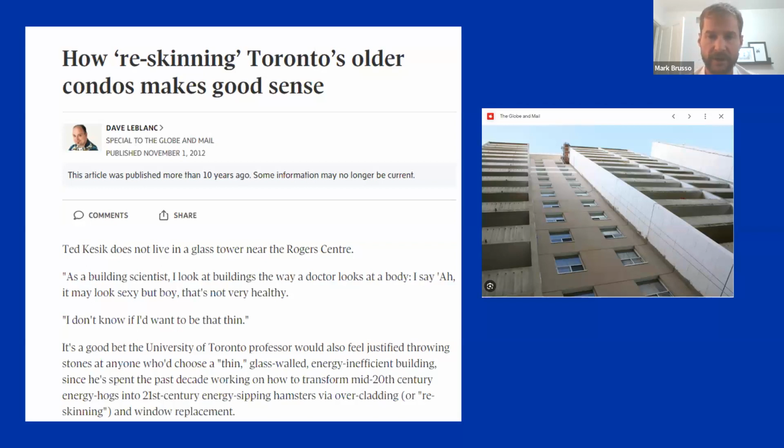These very industrial or brutalistic style apartment buildings were clad in brick, with a lot of raw concrete features, very little insulation and very high levels of thermal transfer, exposed concrete balconies, no thermal breaks. And the dilemma is we had to do something about these buildings to increase the energy performance without compromising the rent income of them.